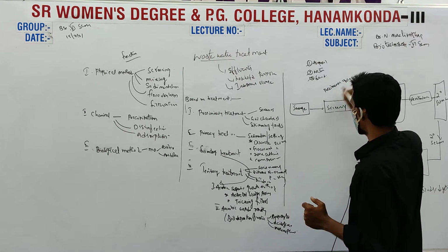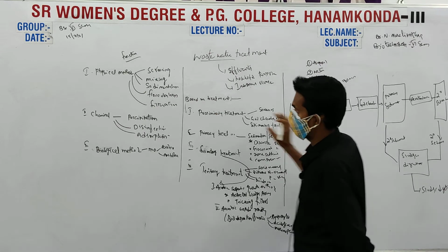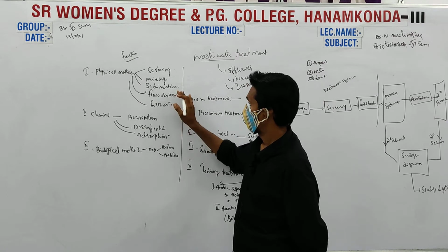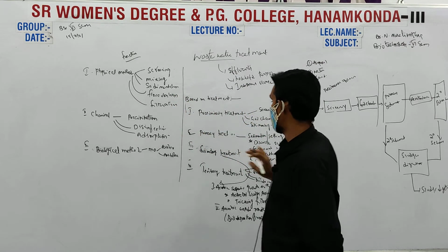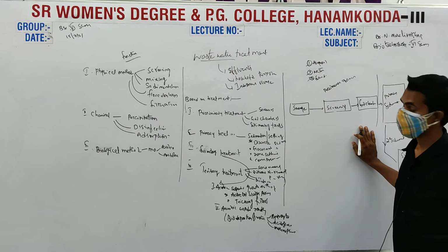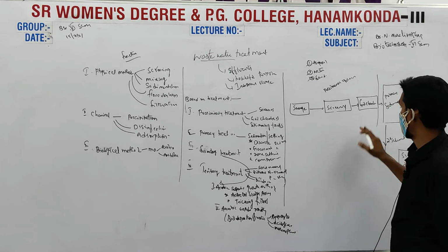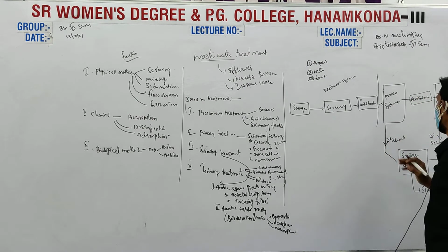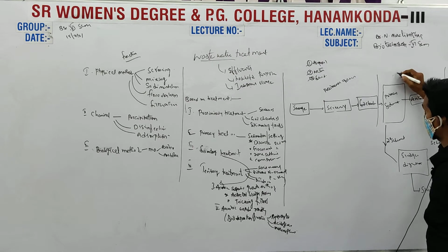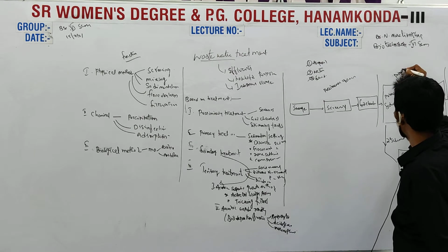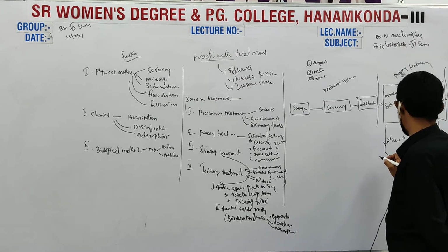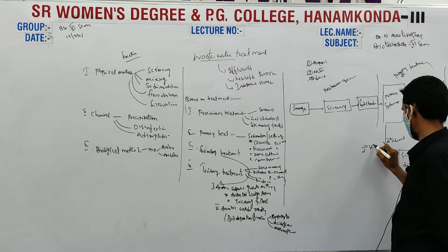In preliminary treatment the sewage has to pass the screening, that is a physical method, and next the grit chambers. From primary sedimentation to secondary sedimentation is called primary treatment, and sludge treatment is called secondary treatment.